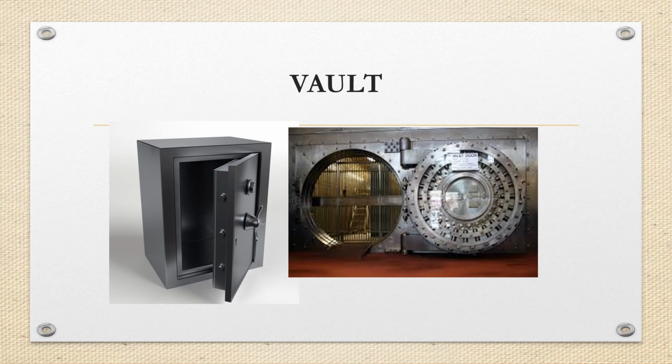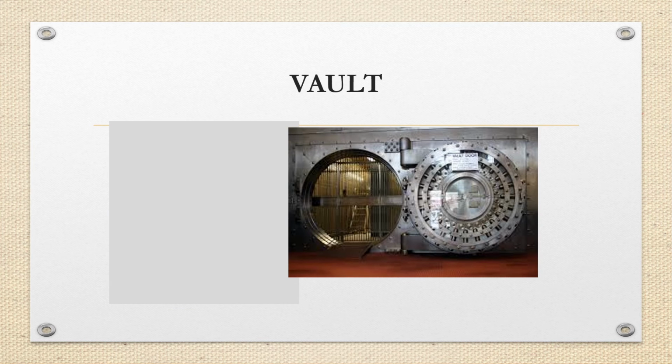The vault door should be at least 6 inches in thickness. The vault walls, ceiling, and floor are reinforced concrete at least 12 inches in thickness, and it is fireproof for 6 hours.